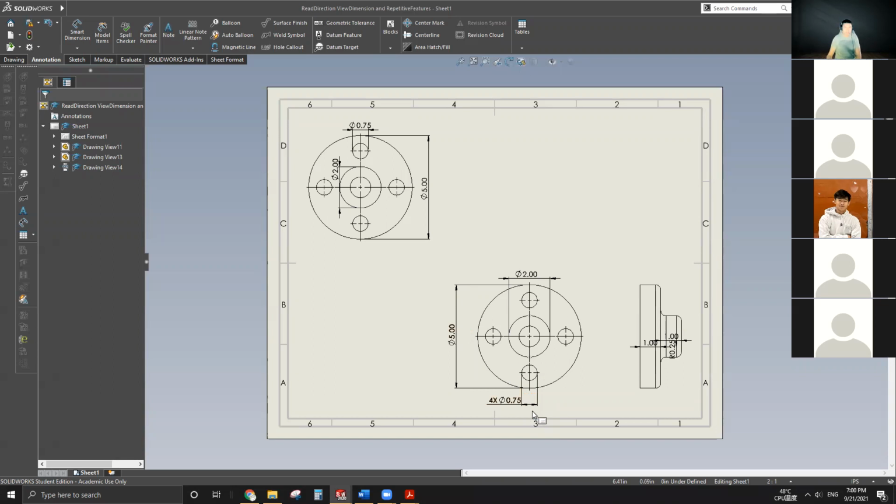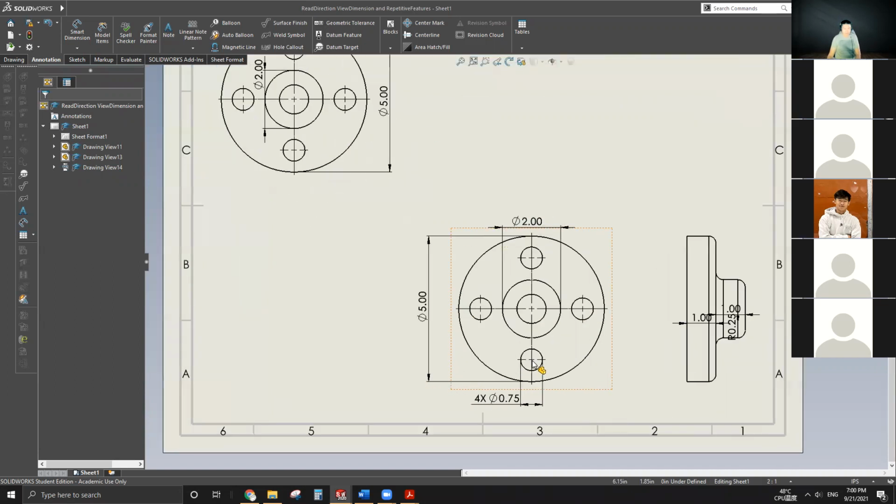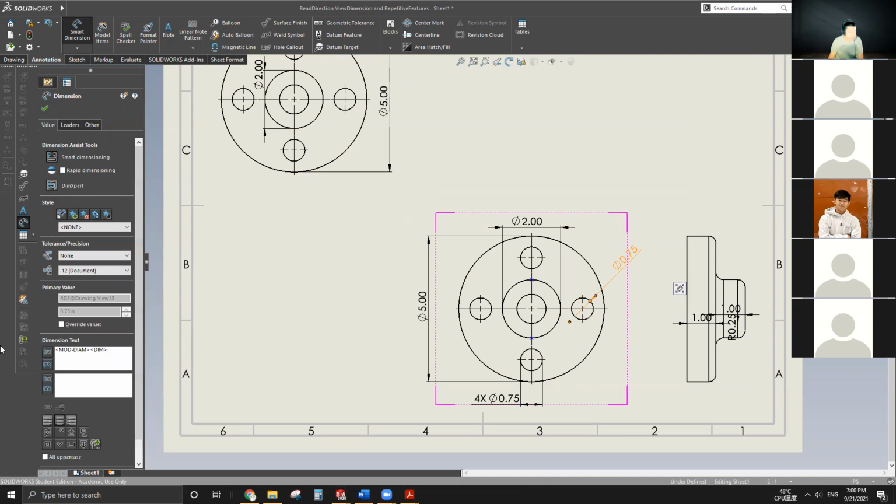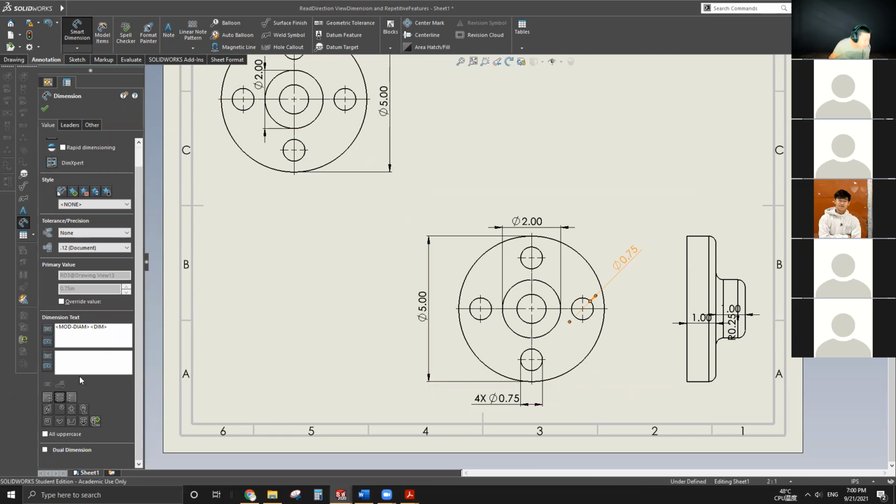Okay. Actually, yes, the bottom looks better, but they're both wrong. And this one is just messy. It pretty much used none of the correct practice. For the bottom one, first, we almost never represent a hole with two leader lines. I say almost never because I've seen thousands of drawings, and if you have a hole, most likely it will look like that.